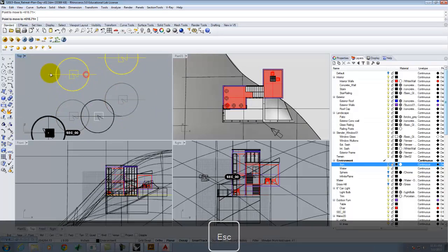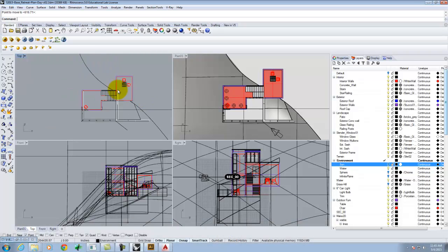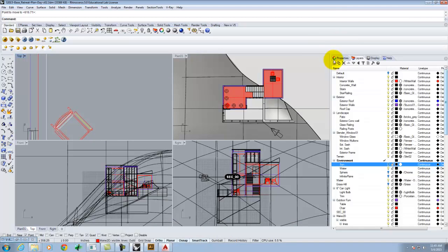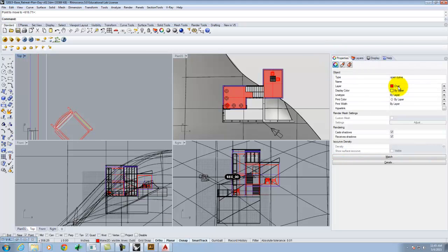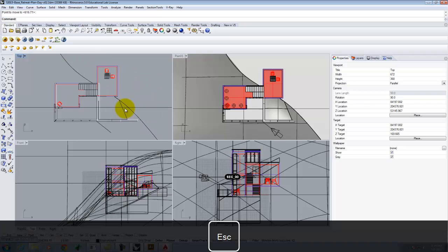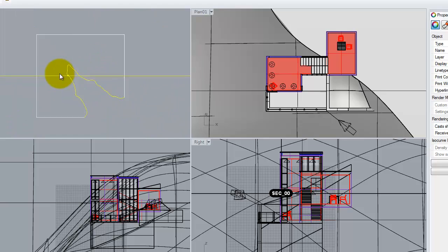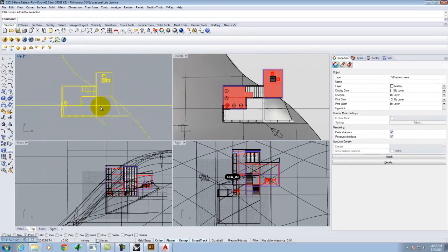let me move this out here. Right, it maintained the source layers. So you see these curves are all on their existing chair layer, which means that when you export it into AutoCAD or you start to assign line weights, you can assign by layer rather than just these are all the invisible objects, these are all the hidden objects. So let me take this set right there,